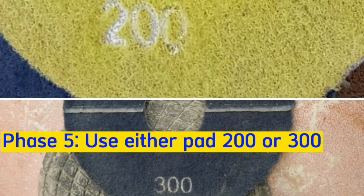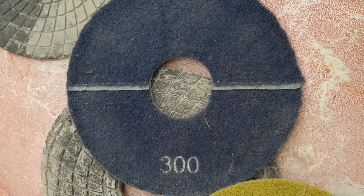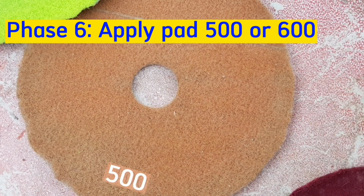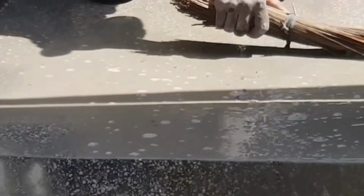In phase 5, we use one of the two pads, either pad 200 or pad 300. Wash the floor with water and then apply pad 400. In phase 6, we apply pad 500 or 600. At this stage, wash with clean water, leave the floor to dry and apply premium polish. If you are considering something smarter and more luxurious, we go to phase 7.